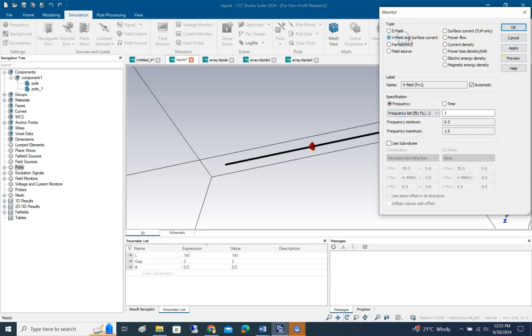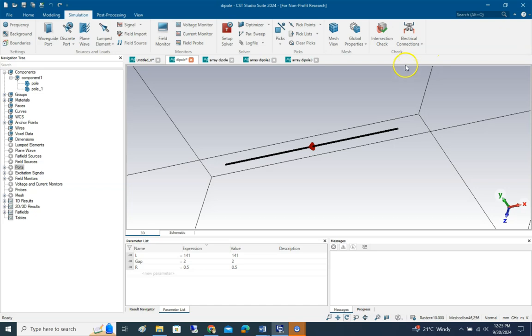If you want to click on that thing, press apply. If you click on that thing far field, press apply. Okay, so this is how you'll be setting up that field monitor so that you can watch the radiation pattern completely, E field and H field and others. Okay, and then you run the simulation, and you'll be watching first.